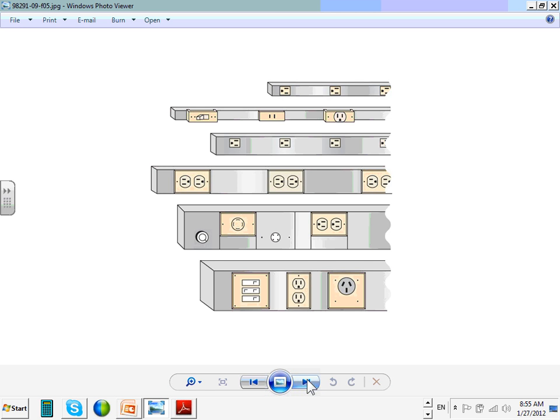Can I go through a wall with the wireway? Like if I have this wireway, can I go through the wall? Yeah, no problem, as long as the section that goes through the wall is not the cover, it's a non-covered section. They have a special section that allows you to open this side and the other side, and the one inside the wall is just complete, like a conduit almost.